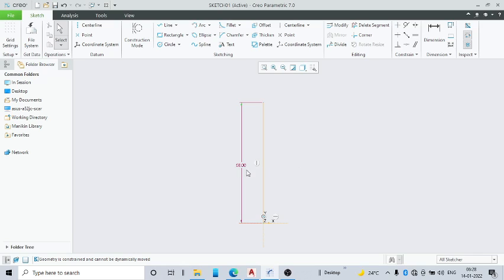So this is the advantage. If you want to move forcefully, you can select this, then click on the toggle lock button. Now it is possible for you to move again, right? So now again right click, double click, then press enter. Now you can see that it is locked. You can try this.